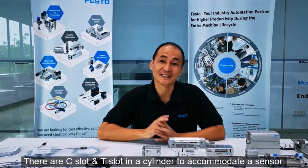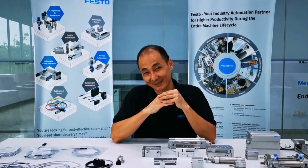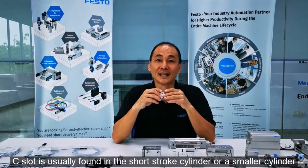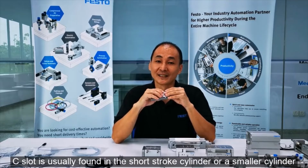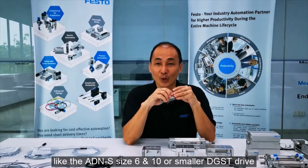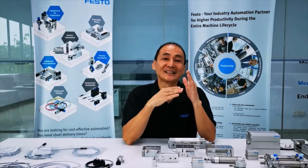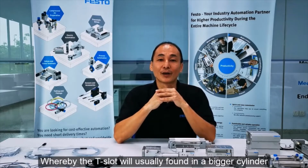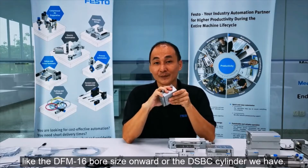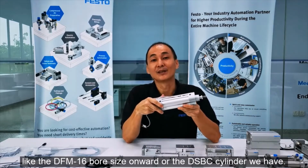In general, there are C slots and T slots in a cylinder to accommodate the sensor. C slot is usually found in short stroke cylinders or smaller cylinders like the ADNS 6 and 10 or smaller DG-ST drive, whereas the T slot is usually found in a bigger cylinder like the DFM 16 bore size onward, or the DSBC cylinder we have.